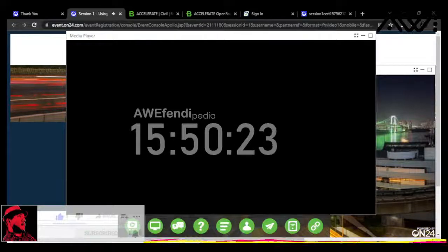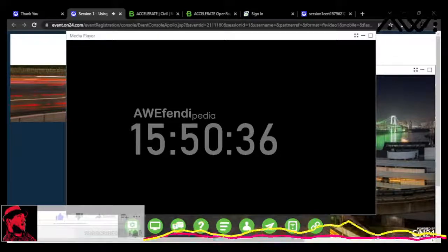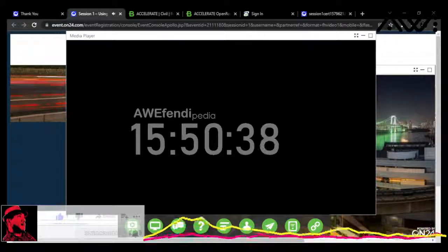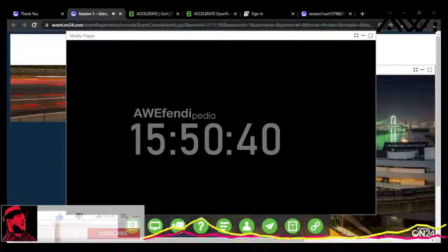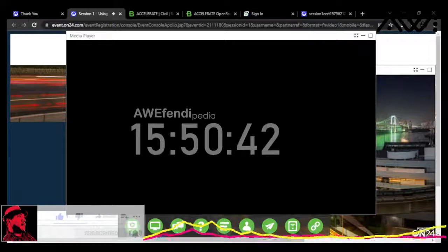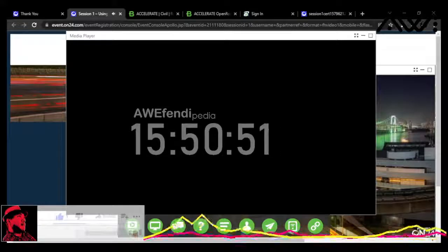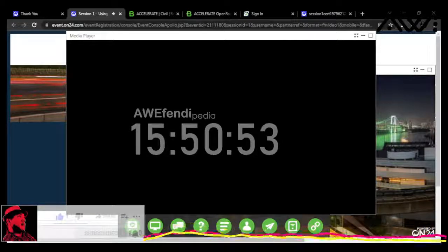While it's loaded, I do want to mention that we're choosing a 3D file to load all of our survey in. There's really 2 occasions where you're going to be working in a 3D file primarily. These are kind of the recommendations I normally give users. We're going to be working in a 3D file when we're importing survey data, and typically when you're creating terrain, existing ground terrain data, you're going to be working in a 3D file. So you'll see me working in those 3D files today.